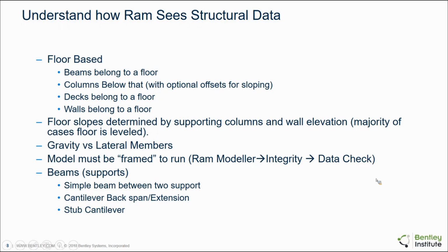So previously we covered how ISM sees data. Now the other players that are involved, RAM and Revit. Let's see how RAM sees structural data. Right off the bat, it's floor-based modeling. That means your beams, columns, decks, and walls all have to belong to a floor.